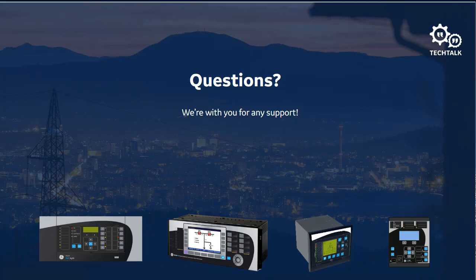Something similar to that might be a generating station, a GSU. A GSU transformer is going to be delta on the generator side and Y connected on the transmission side, for almost the same reasons, to block zero sequence current from the generator. And so in that case, we want to trip for fault currents on that delta side of the transformer. Typically there we would use a distance element that overreaches and reaches through the transformer from the generator.